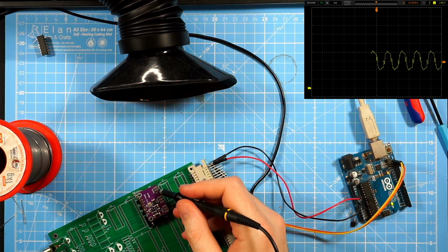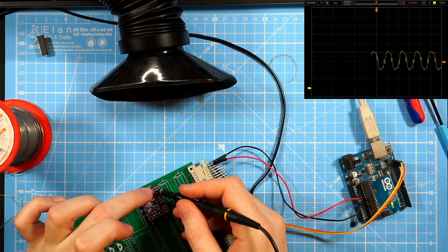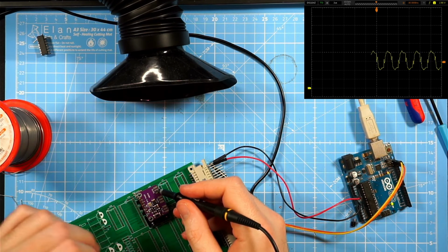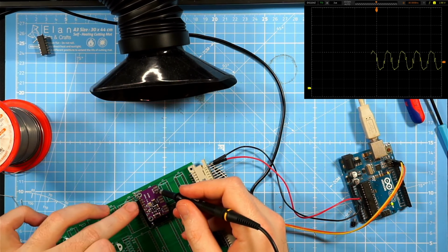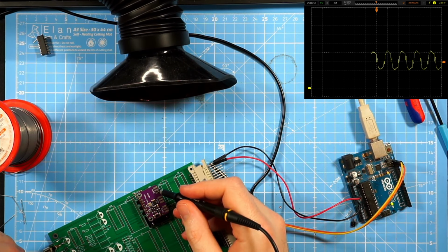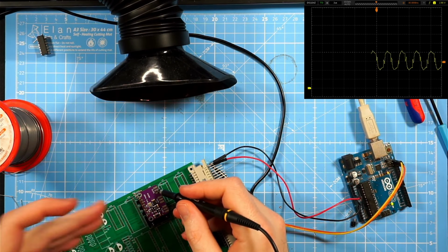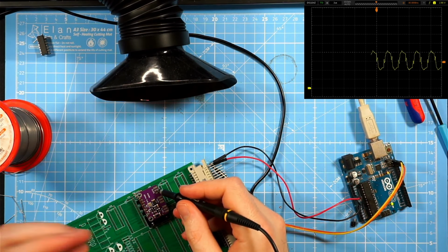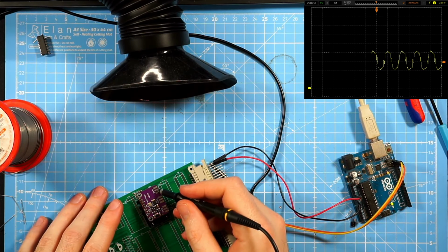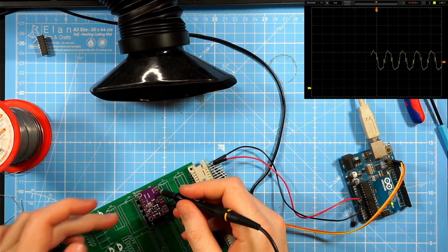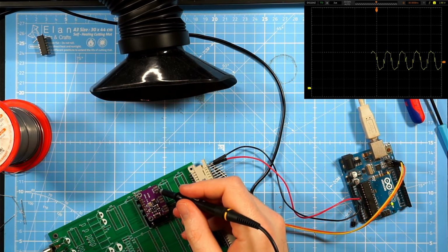And in the next board revision I'll probably use 74HCT04s to buffer those clock signals, and then it's fine. Fixing this is just not worth it right now. If it won't work without those, I guess I have to find another solution, but that's a problem for the future.